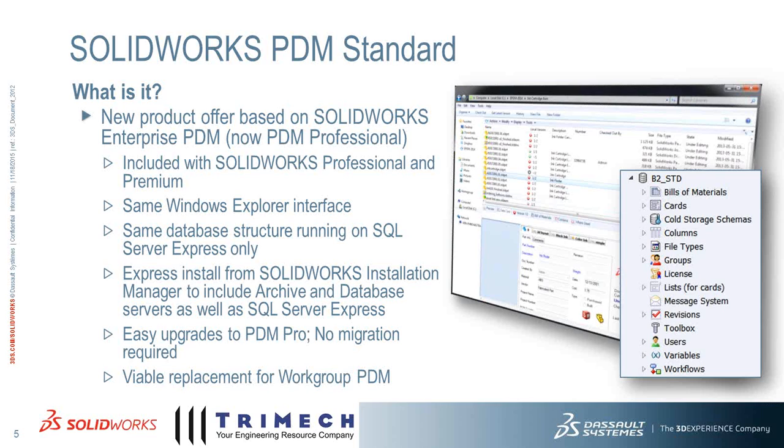It has the same database structure, but now it's running on SQL Server Express. So there are some limitations, going back to who should be interested in utilizing PDM Standard. Really no more than 10 users to access. There's also a database size restriction as well because it's using SQL Server Express. And the Express install is currently available through the SolidWorks Installation Manager to include the archive and database servers as well as the SQL Server Express.